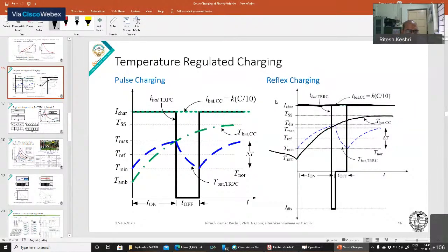So when we see that it reaches a particular charging current level, we stop charging. Whether you charge or discharge, the battery temperature is going to rise, so it is rising further. Then we set another limit here. Two limits basically, something like hysteresis control. Two levels are there.